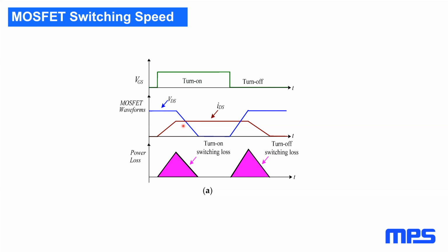There are cases where some driver ICs are really wimpy and have very high impedance. In those cases, quite often, you don't add any resistance because the gate driver IC itself is pretty slow. There are other gate driver ICs which have controlled slew rate, where you also don't put any additional resistance, and you rely on the driver changing its output impedance essentially to change the slew rate.